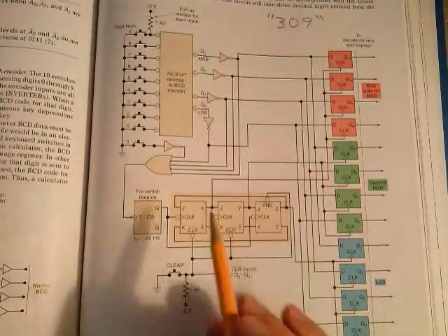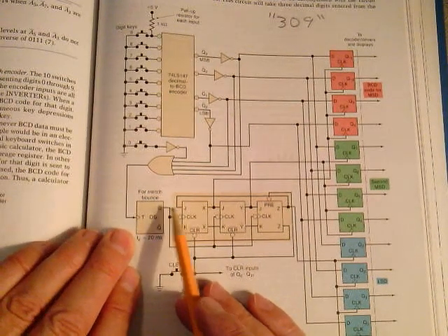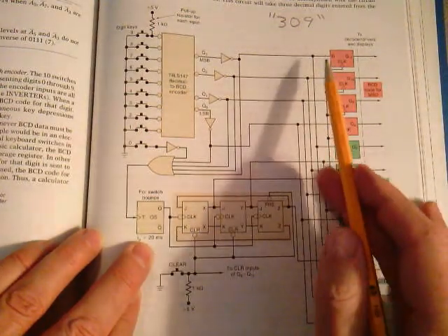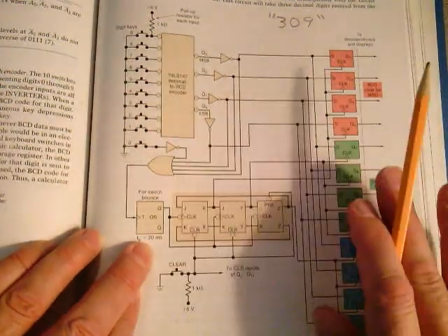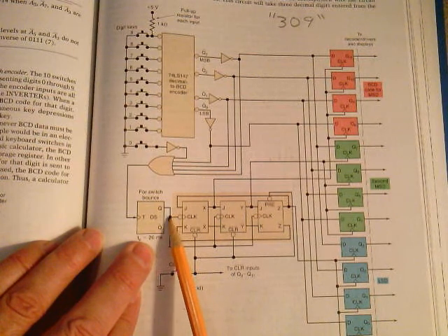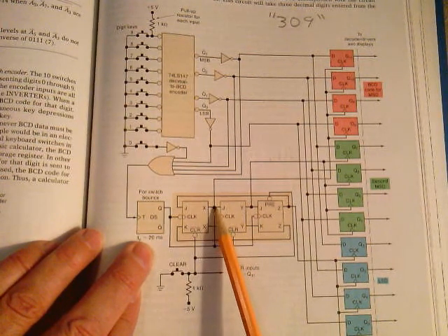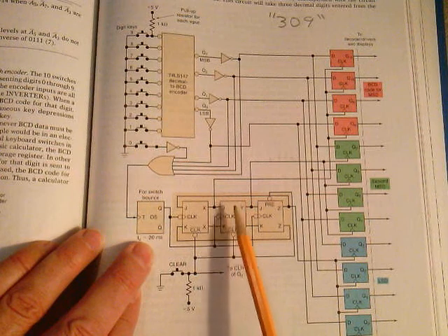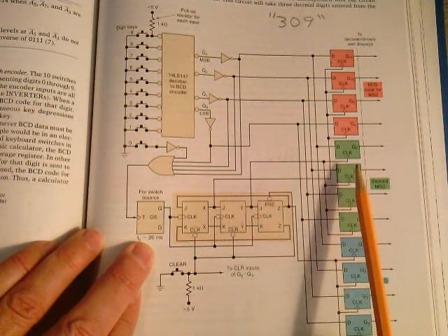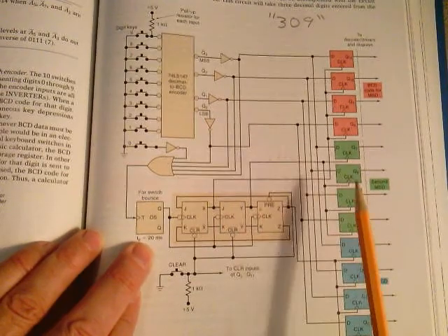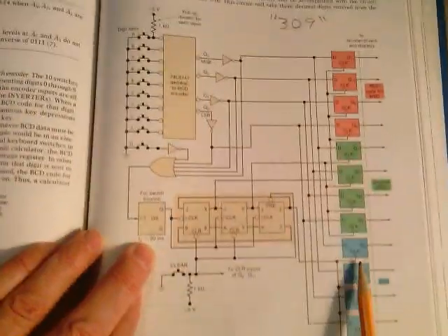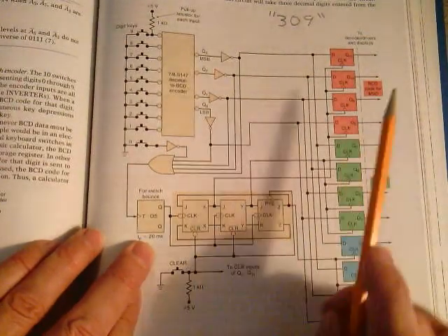But be that as it may, if you look back here, this goes high for 20 milliseconds. That 20 milliseconds is more than enough time for that 0, 0, 0. It all gets settled out here. That goes back to a low. When that goes to a low, it clocks that. This is a ring counter. There's a 1 here. That 1 goes from here to here. Look what that does. That clocks this, this, this, and this. So that 0 only gets put here. Doesn't get put in these other registers. So now you have your 3 here.